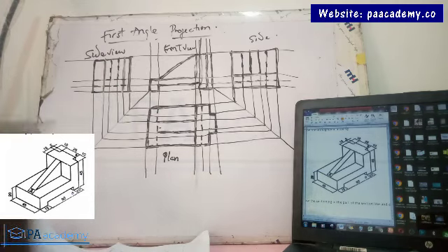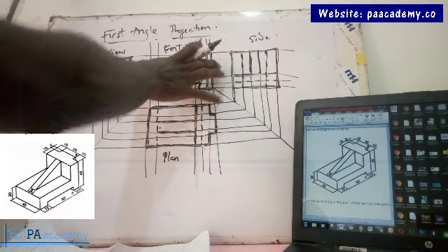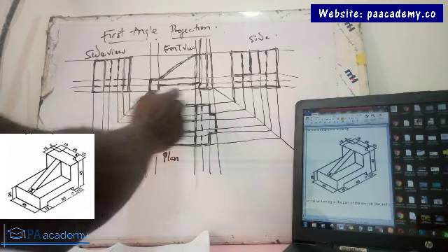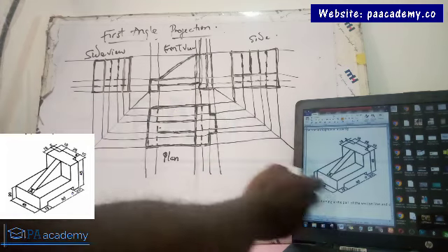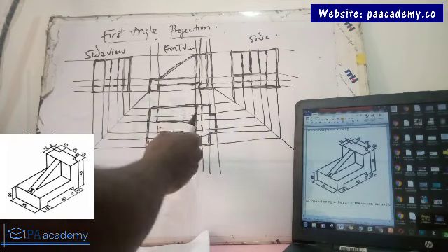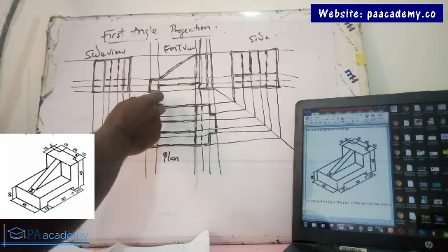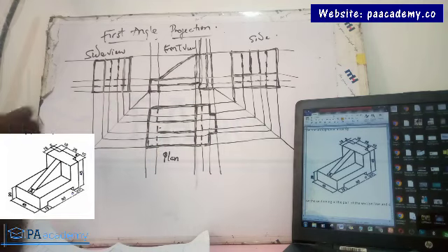So now let's say, for example, you are drawing this front view. Exactly. You have been given the length from here. Now you first need to establish the total length. Exactly. And I think I talked about it at the beginning. Then the length of each individual part. That means if you have to follow what you have here, from here to here is 15. That means the distance from here to here will be 15 mm.